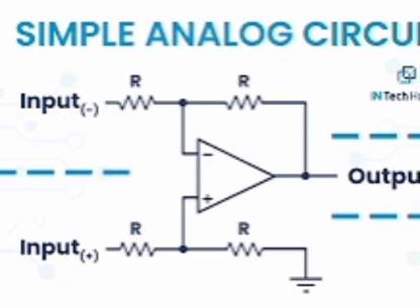Efficiency percentage of half wave rectifier equals 40.5 into RL by RL plus Rs plus Rf. Efficiency percentage of center tap based full wave rectifier equals 81.2 into RL by RL plus Rs by 2 plus Rf. Efficiency percentage of bridge circuit based full wave rectifier equals 81.2 into RL by Rs plus 2 Rf plus RL.